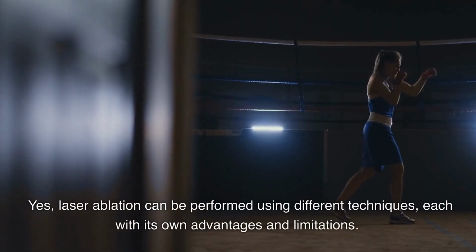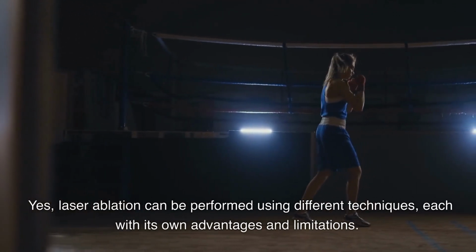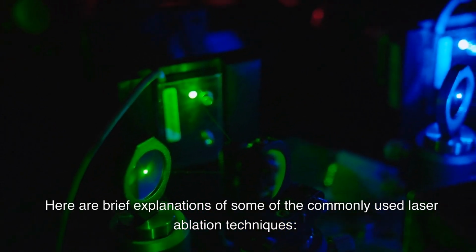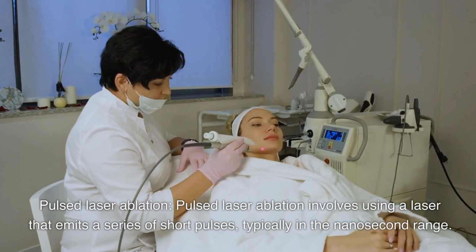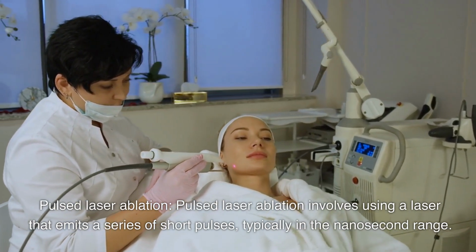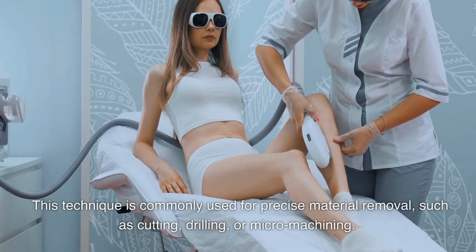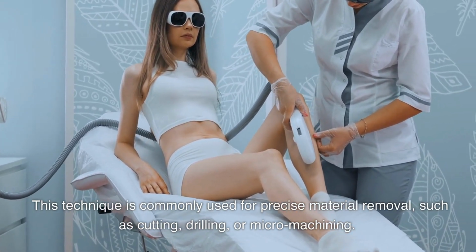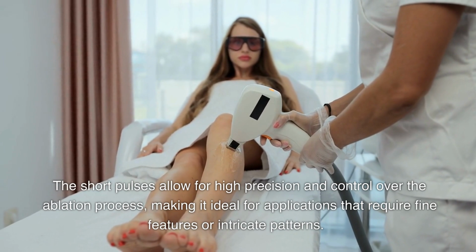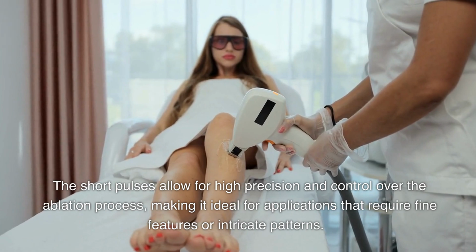Yes, laser ablation can be performed using different techniques, each with its own advantages and limitations. Here are brief explanations of some of the commonly used laser ablation techniques. Pulsed laser ablation. Pulsed laser ablation involves using a laser that emits a series of short pulses, typically in the nanosecond range. This technique is commonly used for precise material removal, such as cutting, drilling, or micromachining. The short pulses allow for high precision and control over the ablation process, making it ideal for applications that require fine features or intricate patterns.